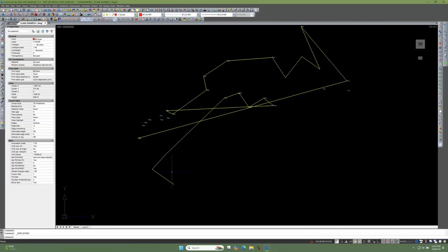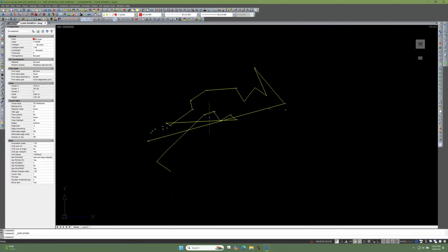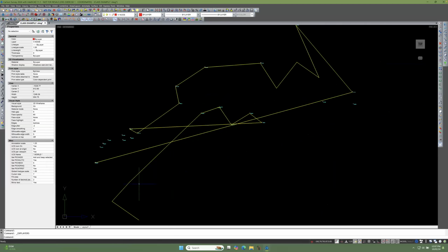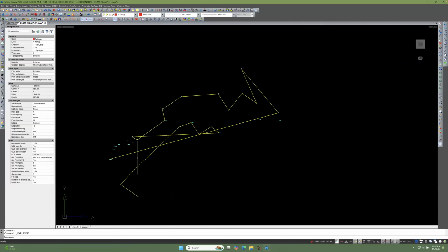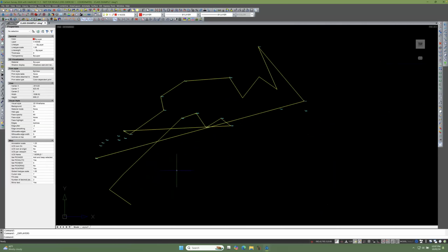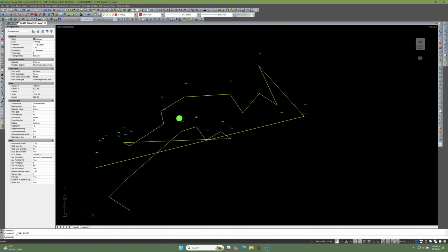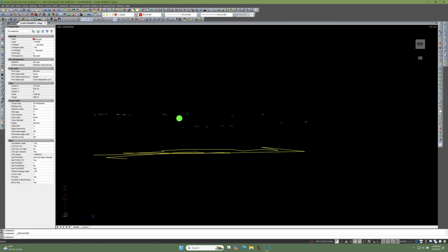So notice I mixed up a variety of ways, clicked stuff in on the screen and moved around, and wherever I picked is where it put the elevations. Now, if you hold the shift key down and press and hold the wheel in on the mouse and push it up, see what happens?